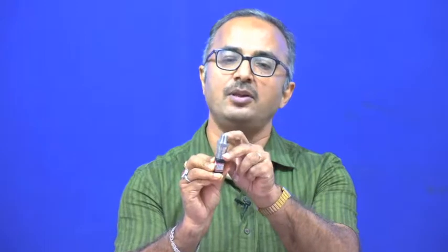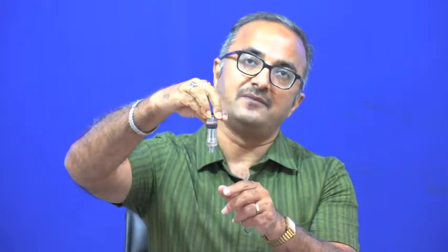Before this, I would like to show you this. This is the pressure transducer. Here you can see there is a small hole, which we put in the transfer line wherever some process fluid is passing, and on this particular hole the fluid pressure is exerted, and this particular portion is a transmitter portion through which the signal of the pressure is transmitted, and from this particular port, we take the electrical signal out from the transducer.